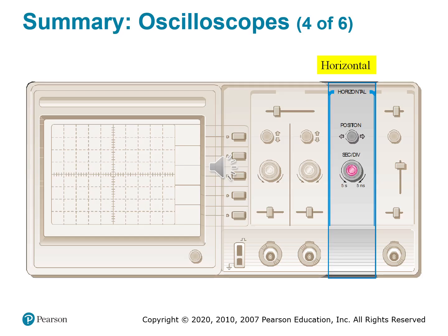Let us talk about the time control, or the horizontal section. Students forget about this one when they get into lab. So you've already seen how the vertical section controls voltage, so let's focus on time. And that's the role of the horizontal section of the oscilloscope. This section determines how the waveform is stretched or compressed horizontally. That's how much time is displayed across the screen.